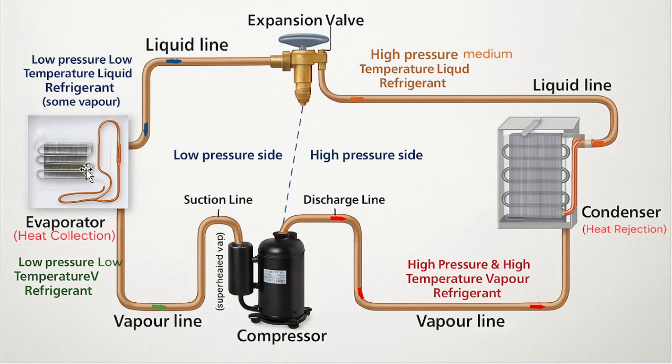Boiling means changing the phase from liquid phase to vapor phase. Boiling needs the latent heat of vaporization, so it has to get the heat. The heat comes from the surroundings inside the freezer or within the room. Now, there is one more interesting thing that happens, okay? Because it takes out the heat, cooling is caused.